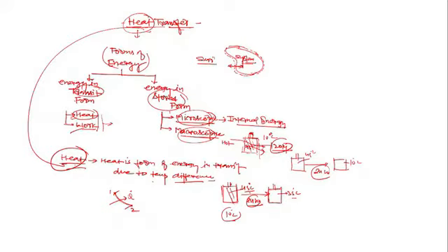You want to keep the water at a temperature of 45 degrees Celsius, because we are in the cold season and we want to maintain the temperature of 45 as long as possible. Here it is best in the sense that the rate of heat transfer is slow, and here the rate of heat transfer is fast. So that's why I'm saying that in designing, the rate of heat transfer is important, because the amount of heat transfer will be the same in both cases at the end of 3 to 4 days.